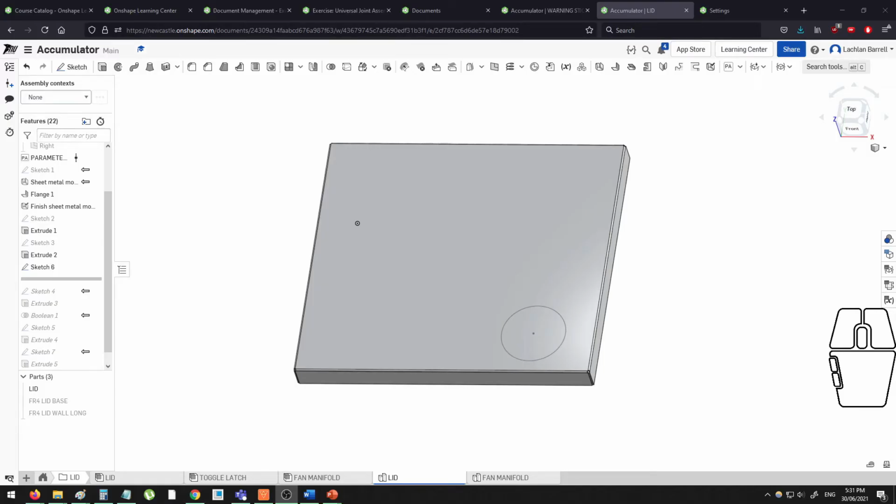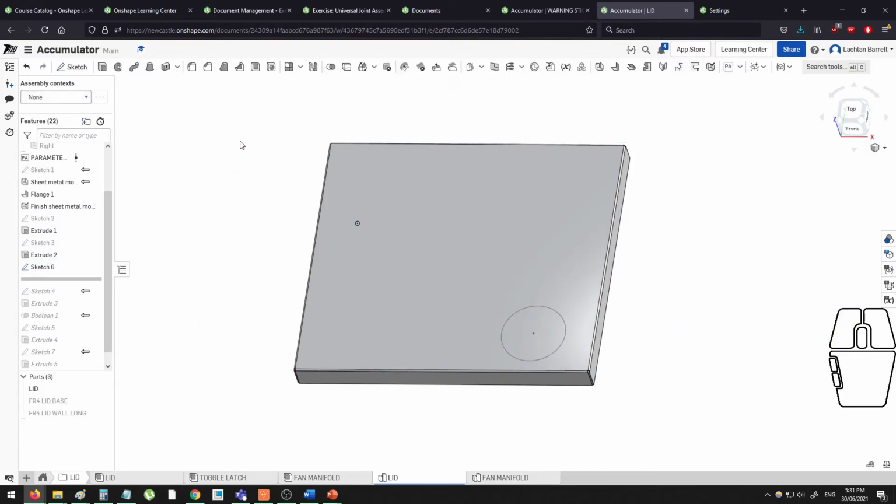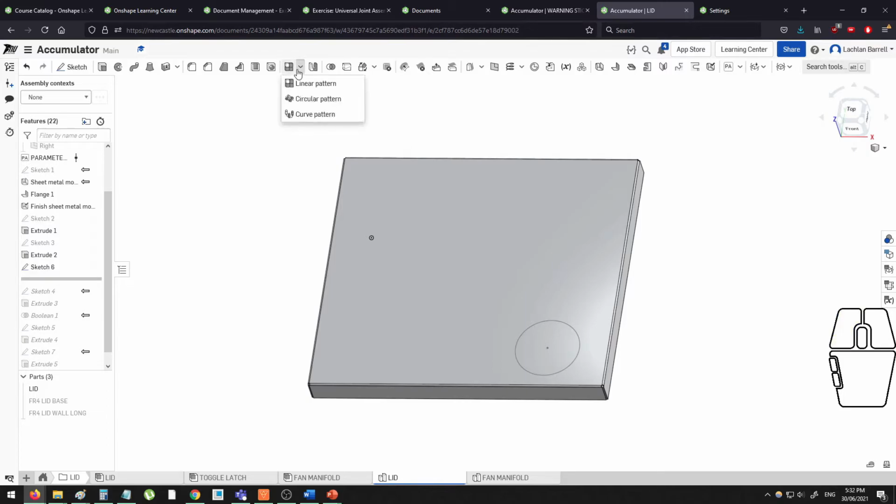Patterns are something that can save you quite a lot of time in Onshape and make your model quite robust and parametric. There are a few considerations that you should be across before you dive headfirst into using them though. So generally speaking, we've got a few different types of patterns. We've got the Part Studio pattern, we've got sketch patterns, and we've also got assembly patterns as well. Of those, usually you'll always see linear and circular patterns. Occasionally you'll see curve patterns as well. They're much less common, and I'll let the Onshape learning pathways discuss those ones because they're fairly complicated.